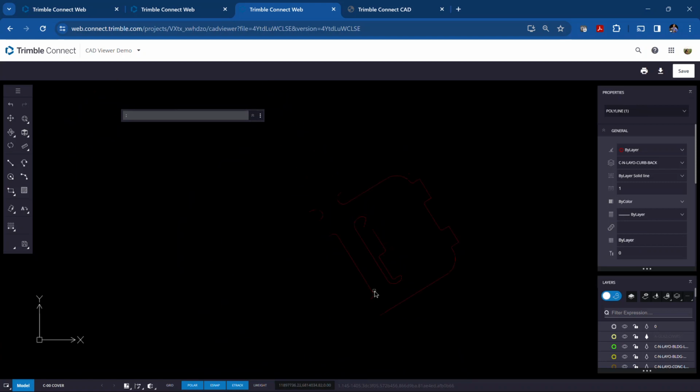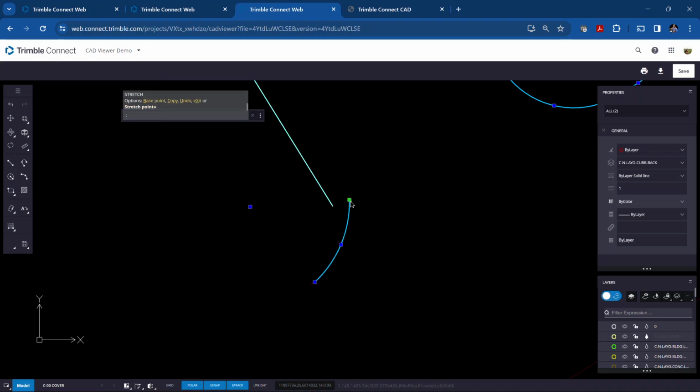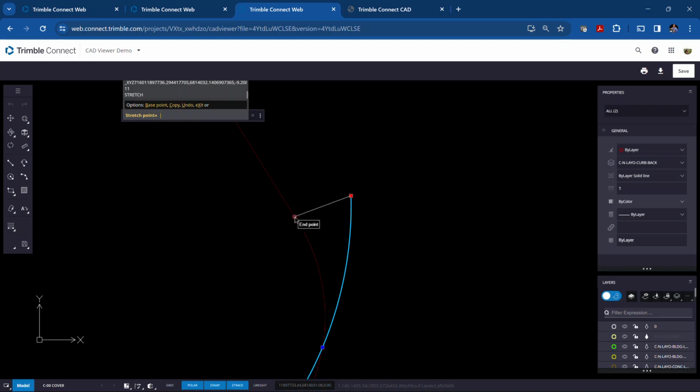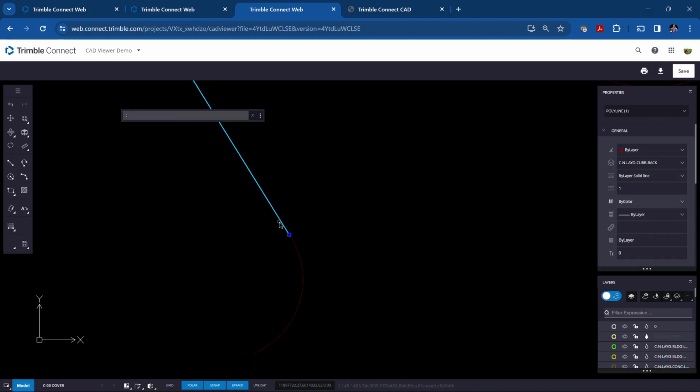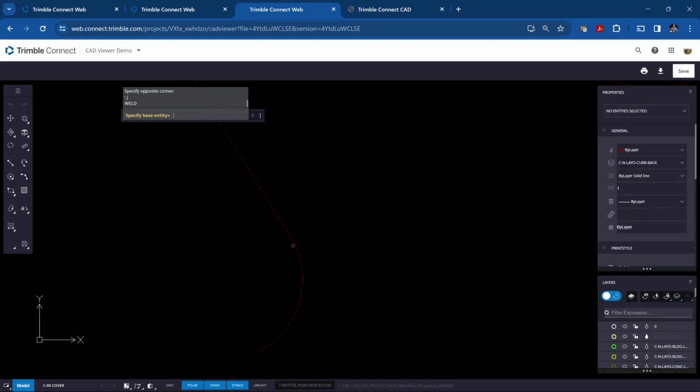So a little bit of editing. This arc here, we can try this, maybe just moving that arc and then snapping it back to that endpoint, and let's see if that works for us. So we do the same thing there. We'll do J for join, press that.